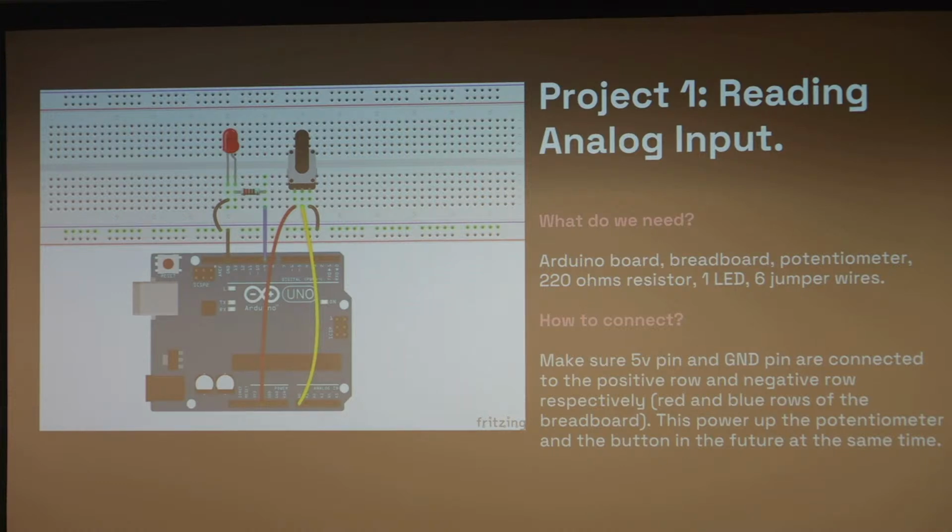I just want to know if we have all the connections right on the breadboard. Yeah, let me see. You try to follow these pictures really closely, although it's hard because they don't have the numbers and letters on the side. Yeah, I know. So you always need to make sure, because I see there's probably a mismatch. You just need to move the potentiometer to the left.